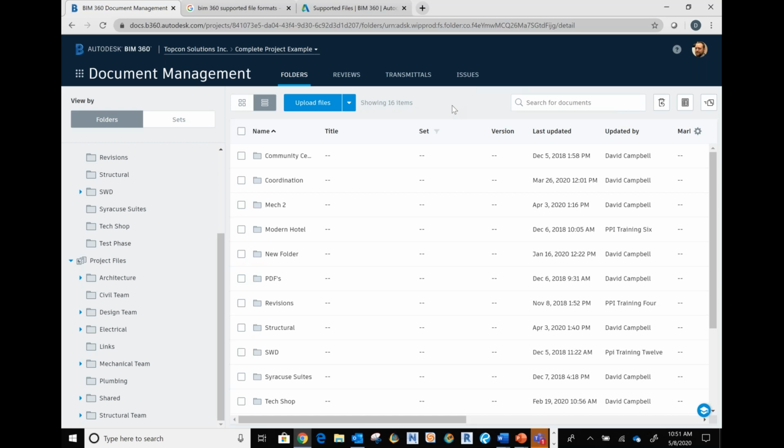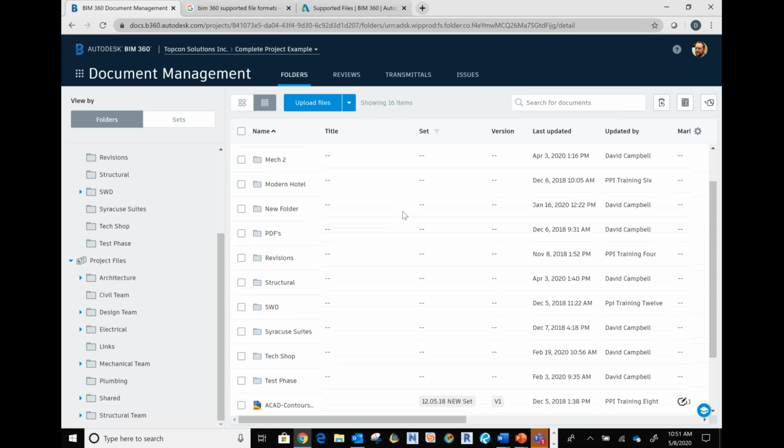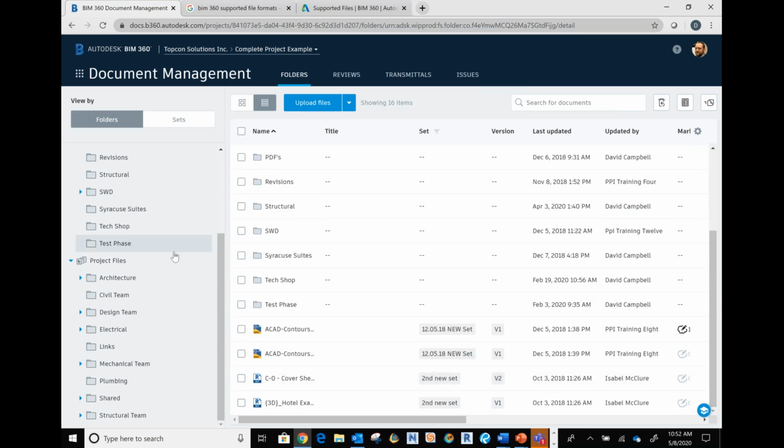The word of caution with storing that much information, when you're accessing any of these files, you notice, and we referenced it here multiple times during the presentation, these items are cached locally on your system. So that's to alleviate load times. You're not loading every single time you sync, you're just loading any changes that have been made. But the larger and more complex those models are, whether they're DWGs, RVTs, NWCs, what have you, the more likely there are multiple changes downloaded with each sync, so the more likely that sync time becomes longer.